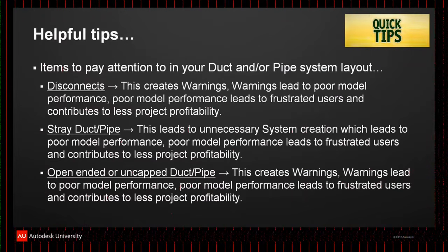It used to be that you could just hit it once. I think in 2012 they started adding a lot of materials, and I forget what the subcategory is that goes along with that, but when you hit the purge one time, you go back into it again, and you'll notice that all of a sudden there's still materials hanging out in there, and you can hit it again. And you might take like 5 times, depending on how far down you want to go.